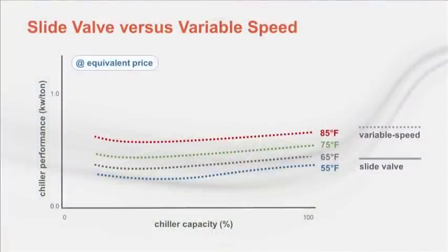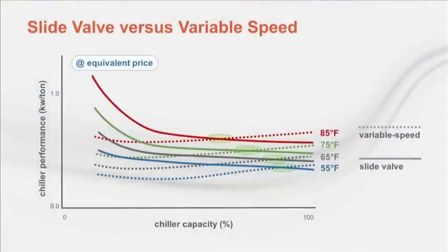When comparing the performance of a chiller model available with and without variable speed, a consideration has to be made to the added cost of the variable speed drive. If you compare the same unit with and without the variable speed, there would be a 2 to 5% hit at full load efficiency that is quickly overcome in part load operation. This graph compares a fixed speed chiller that has improved heat exchangers to illustrate the difference between units that would roughly cost the same. Adding a drive to the unit with improved heat exchangers would certainly improve performance, but a life cycle cost analysis would be needed to confirm the payback for the higher initial chiller cost.